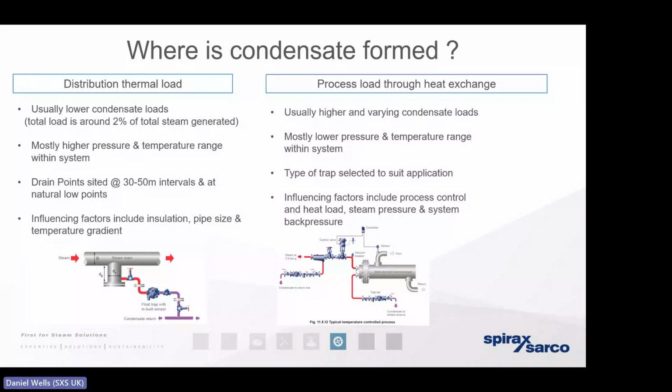So if we haven't sized the heat exchanger to allow for that warming up load, the risk is the condensate is going to back up, it's going to flood the steam space, and we can now no longer get the steam into the heat exchanger. It's flooded with water. So it's going to take longer and longer to get the process up to temperature, and we could be exposing ourselves to a little bit of damage and water hammer in the process.